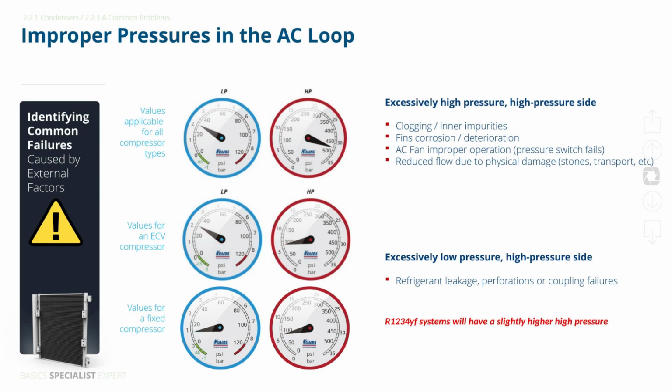AC diagnosis still starts with a pressure check, but modern compressors make things trickier because they constantly adjust pressure based on the car's computer. That's why today you need temperature readings too. The combination of pressure and temperature is what truly reveals the system's condition.